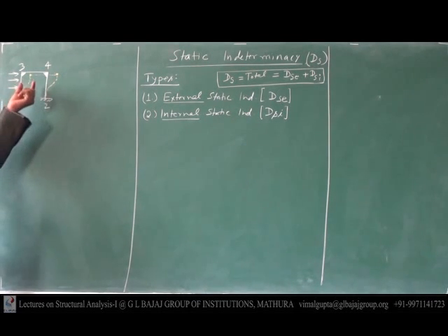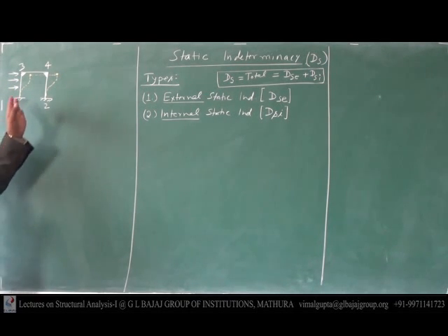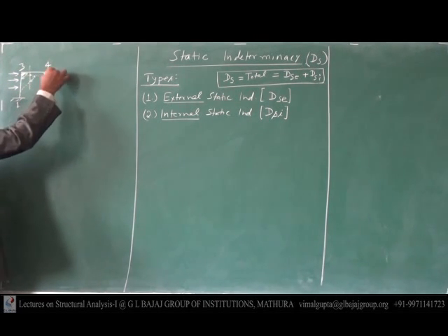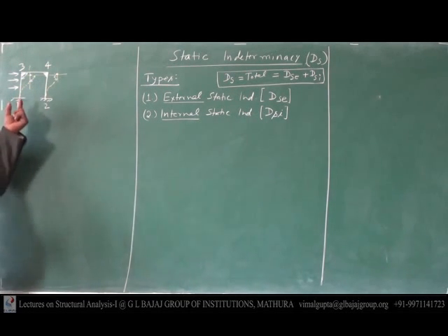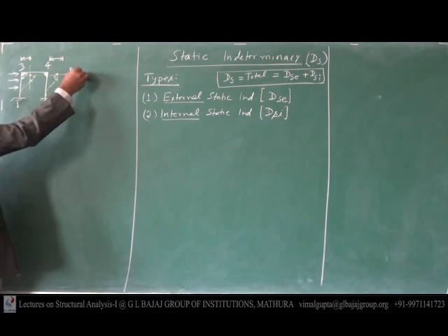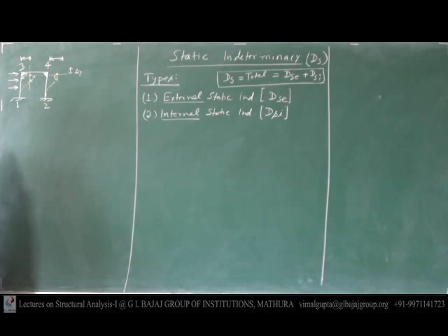What are those movements that we calculated in our last class in kinematic indeterminacy. Here we are seeing that this angle and this angle are 90 degrees. Before and after application of the load, both are the same, here and here also, 90 degrees and 90 degrees. Since it is the same, that degree of freedom, that motion of the structure, will be permitted. So this horizontal movement and that vertical displacement are permitted, as well as rotation.